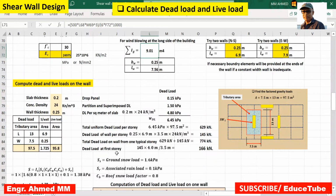Only small difference will be because first story our height is 4 meters, so wall load will be slightly more. How much? 166. So instead of 145, we have to take this load for first story 166.